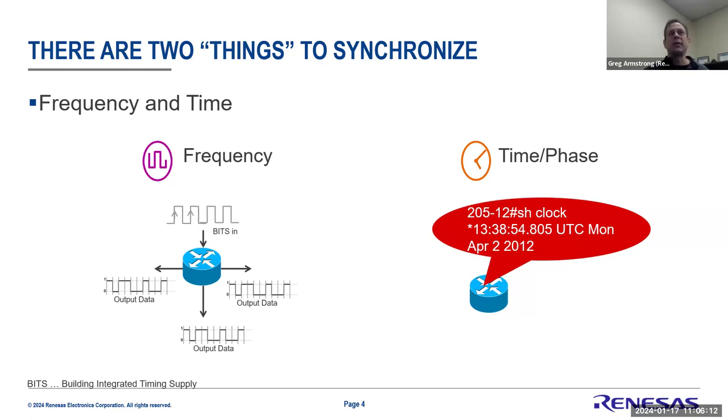That's frequency synchronization. We want that frequency and the phase relationship to be repeatable. But the one thing with the frequency component is that because it has multiple edges, let's say megahertz, when you're looking between two signals, it's hard to say which edge should be my starting edge for the start of measurement in relationship to another edge.